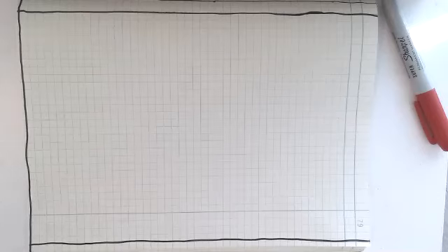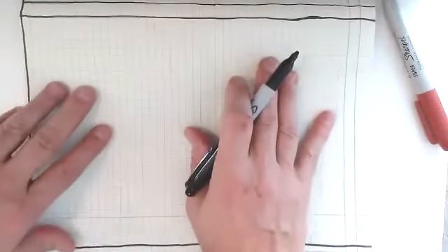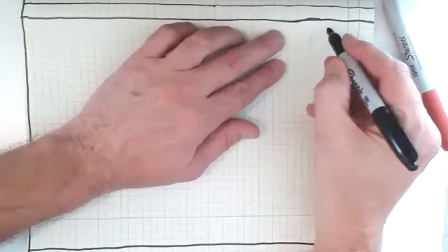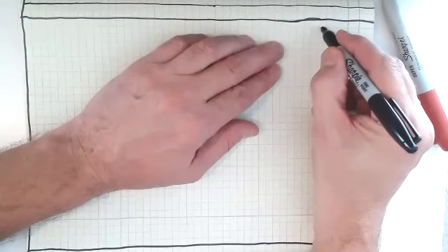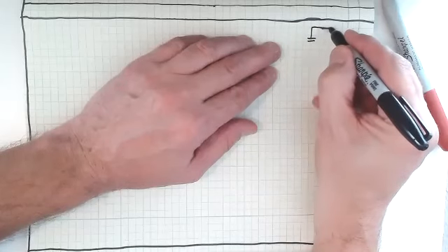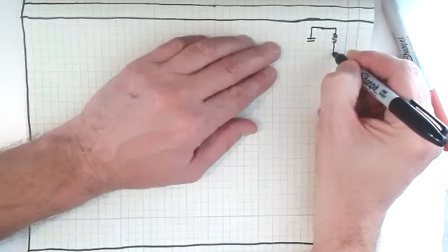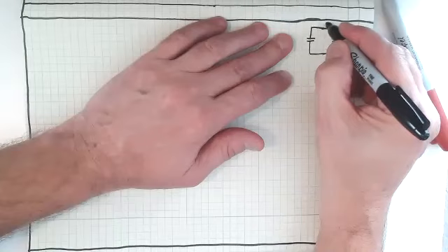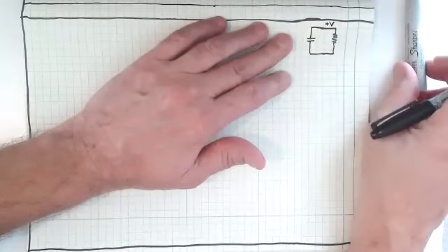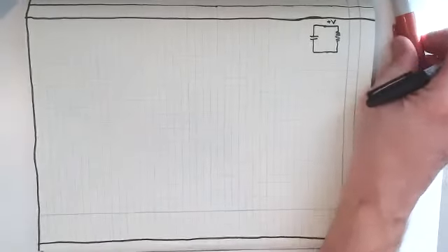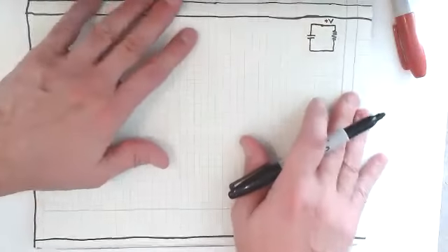So what I want to do is look at the first order source-free RC circuit. In fact, I'm going to follow very much along with what your book has. Now, when we look at a source-free circuit, we're looking at the node, and of course the node includes all of that top section. I've got a resistor here, and I've got a capacitor. We've left some type of positive voltage up here. We don't know what that is because we've just removed the source, and we don't know if the capacitor is entirely charged or if it's partially charged or what.